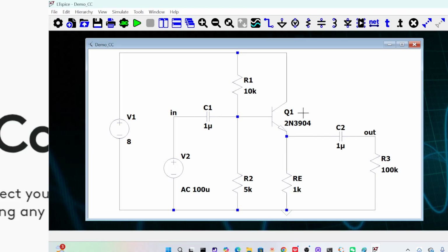First of all, we need to know that an oscillator is not the same as an amplifier. In an amplifier, you might have R1 and R2 here to maintain a stable bias circuit. But in oscillator design, you are going to use the output to feed the signal back to the input.